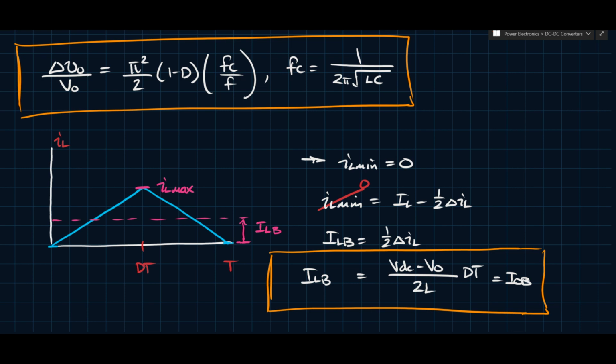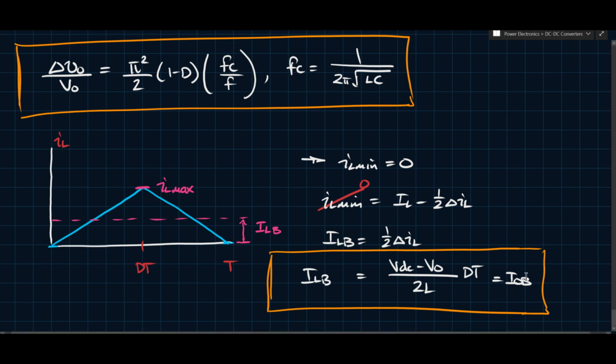So it's usually easier, and much quicker, to calculate the output current, because you just take the output voltage and divide it by the output resistance in a resistive load, for example, and then you know what's going on. Or you have a load that has a specified current. So you know what IO should be, compare it with IOB, and then you know which mode you're in.